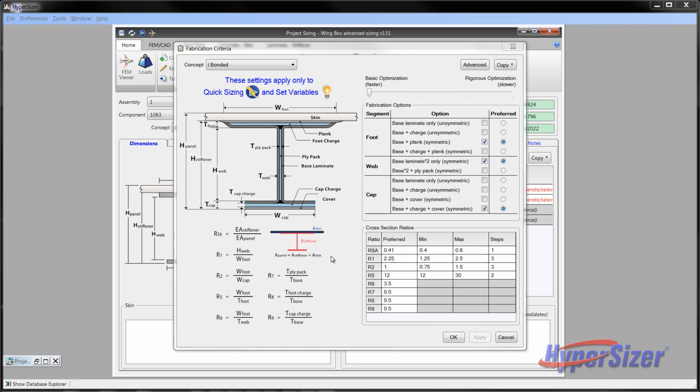For discrete source damage containment, designers usually stay within the bounds of 40 to 60%. A lower value tends to make the skins thicker and the stiffeners spaced further apart, requiring less overall panel stringers in your structure. The other R ratios and their settings are based on similar industry best practices. They also account for repair rules and help the sizing optimization to more directly define panels that will satisfy these.